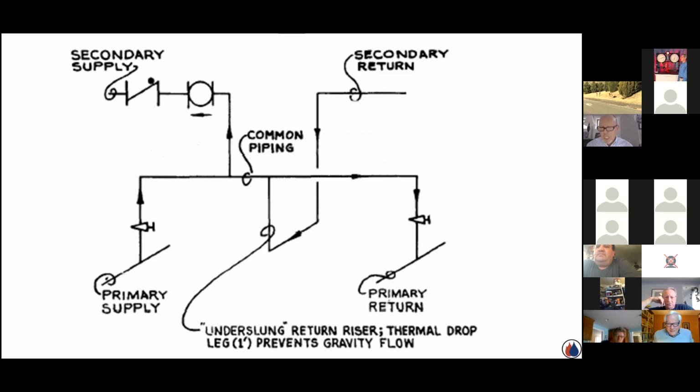Most days today, we're going to have copper piping or even PEX tubing, so the diameter and the volume of water in that system is much less. You usually get away with a flow control valve on the supply and you're fine. But every now and then, the moon and the stars align, and we have this situation where it's set up and we get some reverse flow, not reverse flow, but some migration, thermal migration. And the quickest way to solve it is just to throw that second flow control valve on the return.